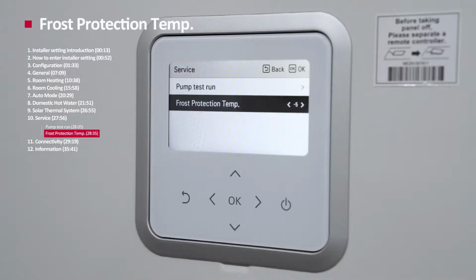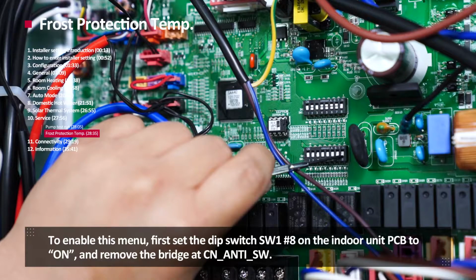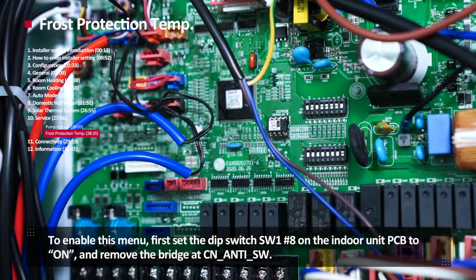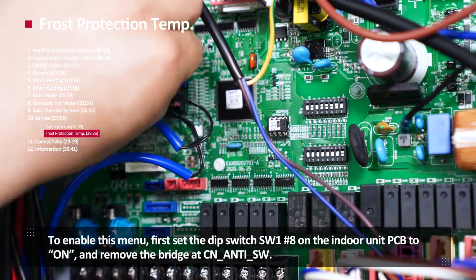Frost protection temperature. Frost protection temperature function is used to set the offset temperature for the freeze protection logic. To enable this menu, first, set the DIP switch software 1 number 8 on the indoor unit PCB to on, and remove the bridge at